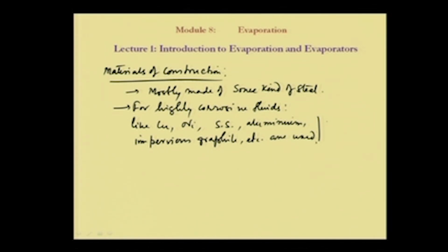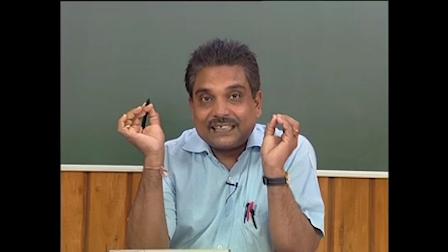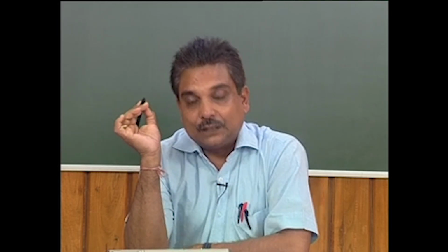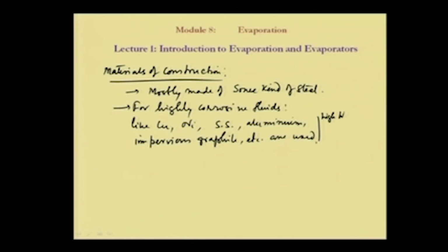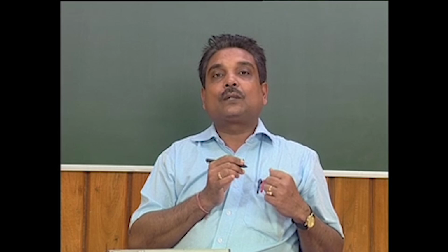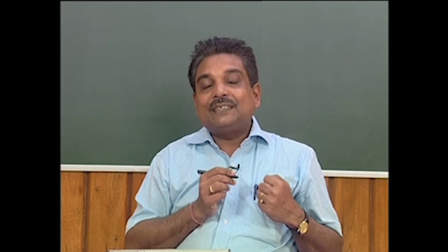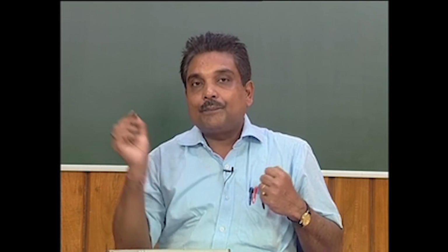This is because a higher heat transfer coefficient means we need less surface area, that means less consumption of these materials. So, that is one important criterion, that we should have a high heat transfer coefficient to reduce area or size. Actually, the intention of anybody would be to reduce the area of heat transfer, and this will always reduce the capital cost investment, but sometimes it may not be possible due to some external constraints.